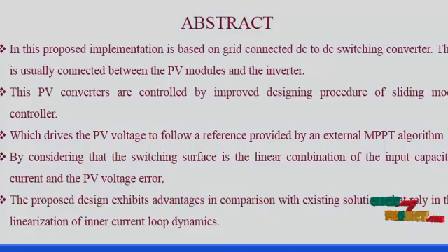The proposed power and frequency characteristics of the hybrid unit and of the microgrid operating conditions are such that the hybrid unit may supply the maximum PV power, match the load and/or charge the battery while maintaining the power balance in the microgrid and respecting the battery state of charge limits. These features are achieved without relying on a central management system or communication, as most of the existing algorithms do. The control strategy is implemented using a multi-loop controller, which provides smooth and autonomous transition between the operating scenarios, and this proposed implementation is done in the MATLAB simulating environment.